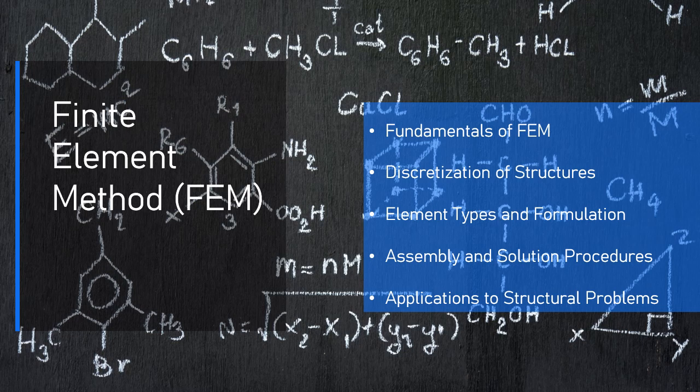2. Local refinement. In some regions where there is high variation in stress or deformation, e.g., around a crack or concentrated load, the mesh can be locally refined. This means that smaller elements are used only in critical regions, while larger elements are used in less critical regions. This process is known as adaptive meshing, where the mesh is refined based on initial results or known areas of high interest.